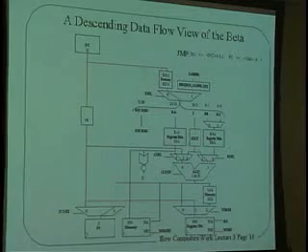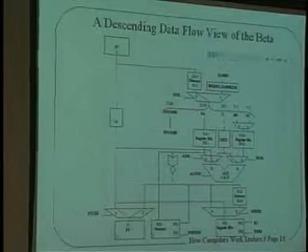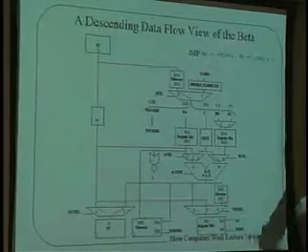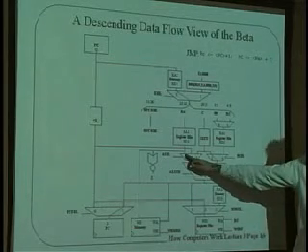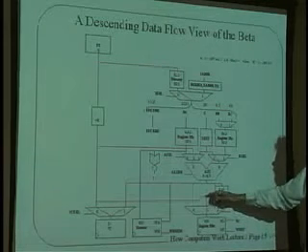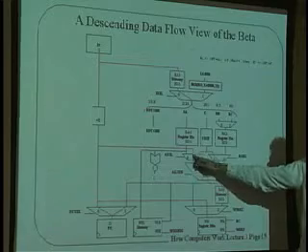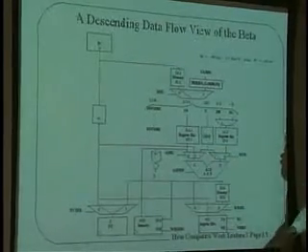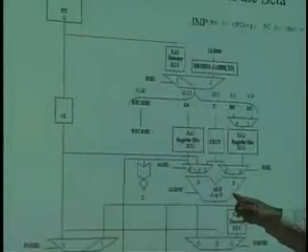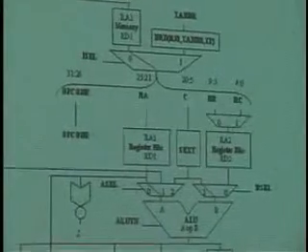Okay. A jump. A jump is very similar to a branch. Let me go back and forth here. What is going to change? Isn't this cool? I'm sorry you can't see it, but this red shifts from here to here. Well, you can at least see these things moving, right? Yes, I can. And so instead of saying that we're going to take the PC plus 1 and add C to it, what are we going to do? We're going to take the contents of RA and add C to it. And that's what jumps do, right? Contents of RA plus C goes into the PC.